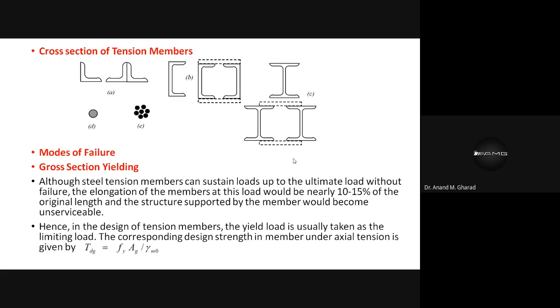And what will happen, the load carrying capacity gets reduced, isn't it? So the plate which was solid has now been reduced to a small plate, and the overall capacity of that plate will again reduce. But even so, if we maintain the distance between these holes in a correct manner, then the collapse capacity may be increased.